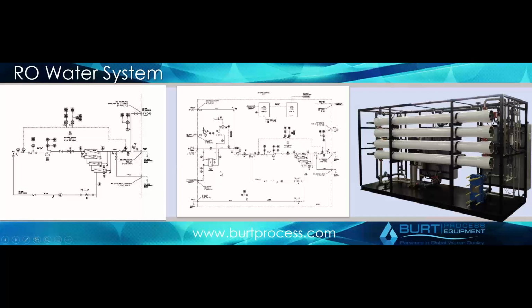The bigger your RO system, the more you want to try to optimize its performance as much as you can, because reject water is essentially a waste. You're taking your city water source, your well water, whatever your water feed is, and you're going to be sending 50 to 25%, maybe 20% if you're optimized, down the drain, essentially. So it does become fairly critical in that regard to do that. If you have, for example, say a 50 GPM system, you're always dumping 10 GPM down the drain, as long as that's being utilized in that case. So it's very important to definitely want to optimize your RO in larger systems.